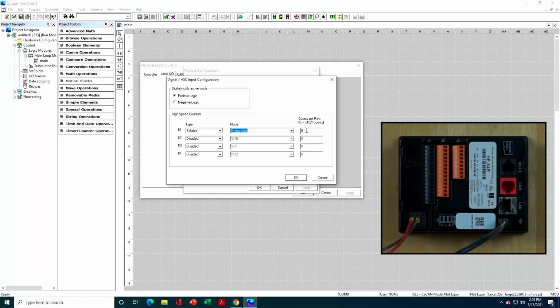The only time you're going to set that to some non-zero value is if you are using an encoder, and in the application, it's a rotary application where there are a maximum number of counts per revolution, and you only have exactly 1 revolution for your mechanical system. If you have more than 1 revolution, you'll still leave that at 0.